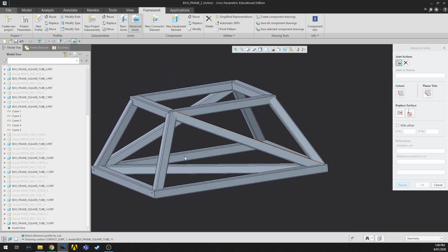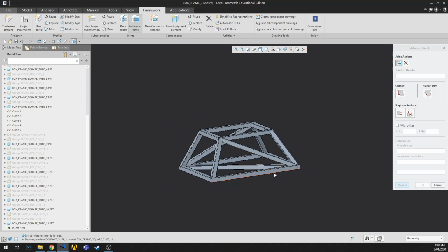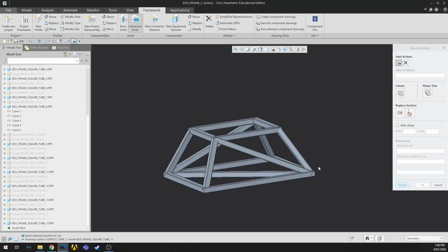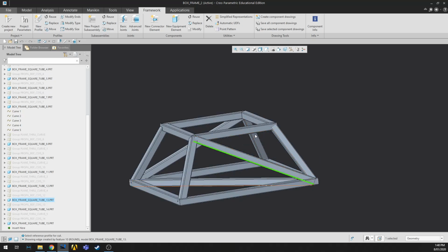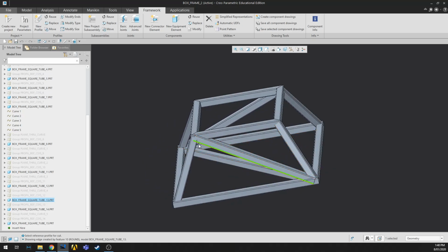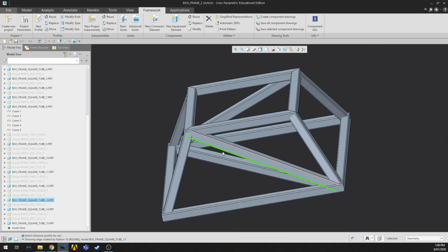Yeah, so no great examples I could show here, but if you think to the chassis, you'll often have tubes that go in as triangulating members, and if you don't notch them in an appropriate order, particularly when you have nodes with like 4 or 5 members coming together, you need to notch them appropriately. Say we were triangulating on this member here, we were going to make a node here and we want to triangulate that. Maybe we were putting a cross brace in or something. You would leave this member as is and only notch it to the top corners, and then the member going through here, you would notch both. That would give you more strength and less cuts.